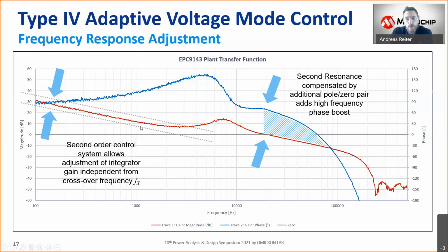So we are using this two-sided tuning concept now to balance out the step response. So how fast can we recharge the output capacitor to minimize its size? And the second thing is then whatever output impedance is required to meet of this decoupling cap can now be adjusted by adjusting the integrator gain.